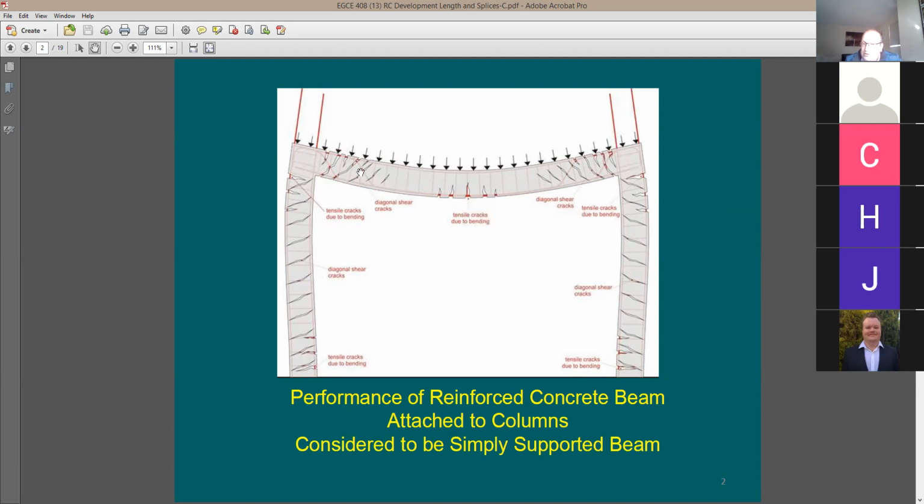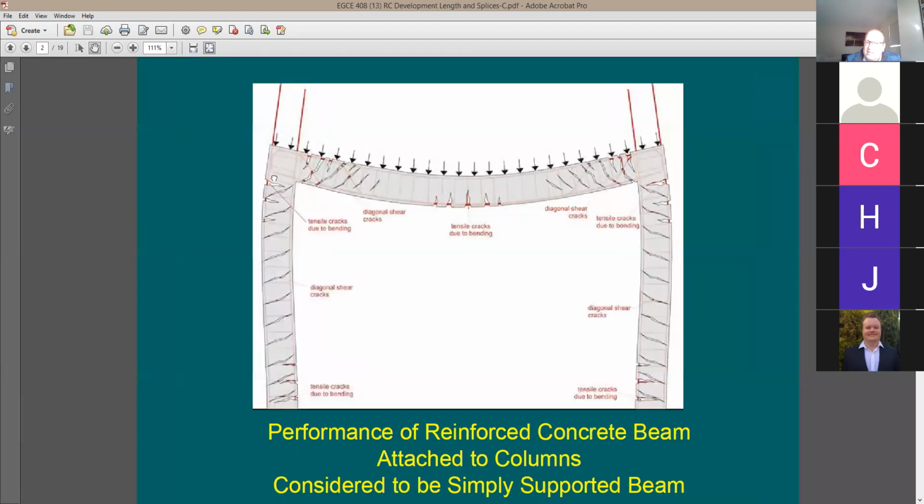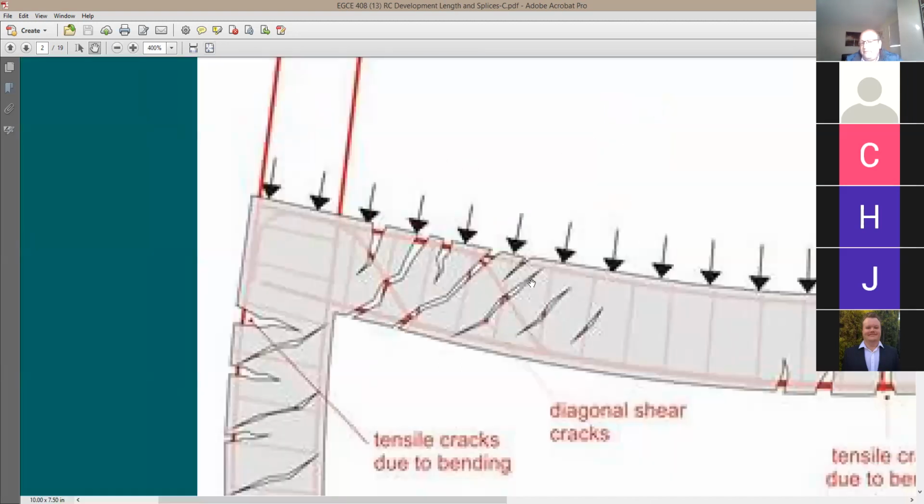But when you put the reinforcing together and you put the concrete beam, whether you want it or not, this end here is going to develop some moment. So it is not really a hinge. So in your analysis, you assume that here you have a hinge, but in reality, you don't have an actual hinge. Let me look at this from a closer look and see what happened. Look at the reinforcing. The top reinforcing usually is going to be provided with a hook at the end.